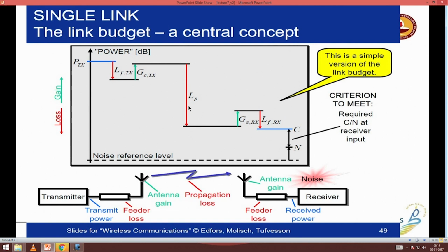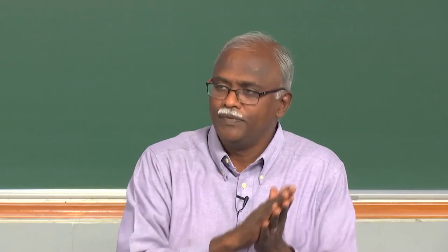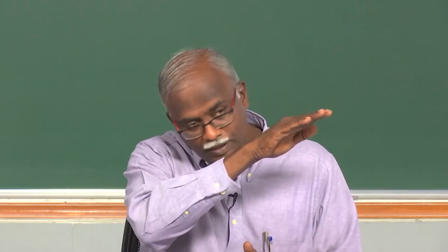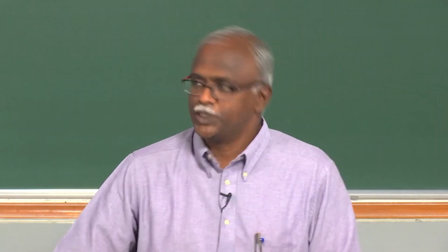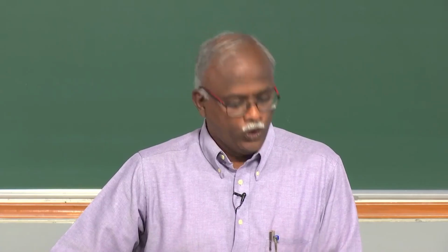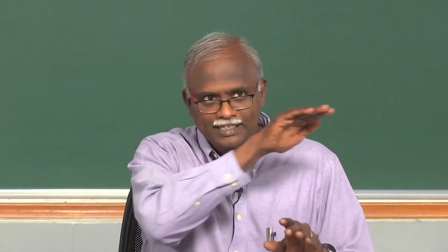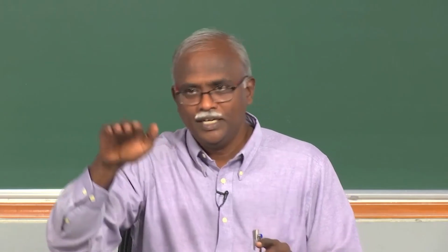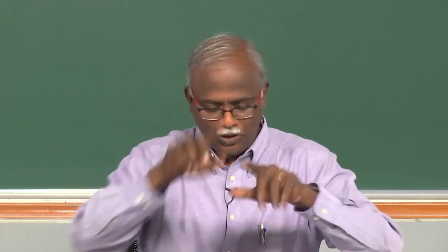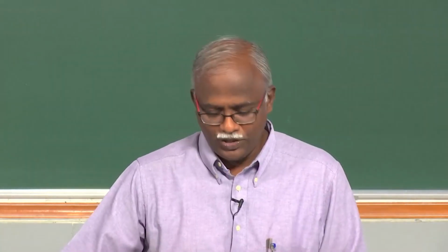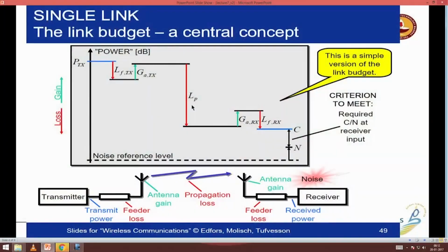Now the path loss itself may have two components or three, depending upon the model that you have used. We have used the simplest model, where you have a single breakpoint, which says line of sight or free space propagation up to D break, and then a higher path loss exponent post the D break. Okay, so visualize it as signal level, gain, loss, path loss, receive antenna gain, margin, and basically you go up and down, but make sure that you are moving in the right direction so that you get your path loss calculations correct.